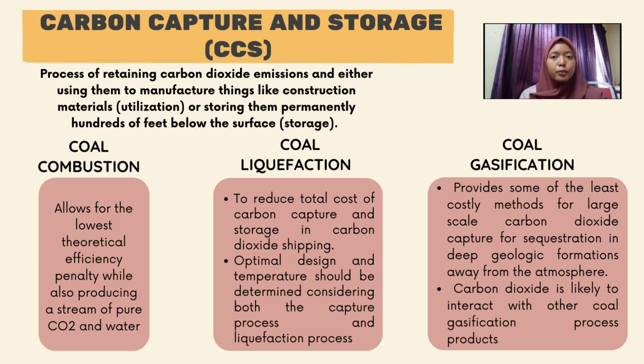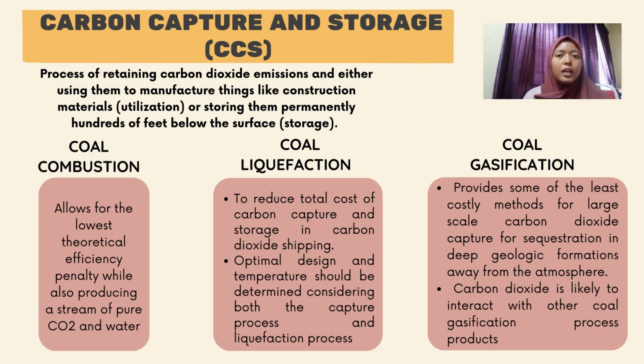Optimal design and temperature should be determined considering both the capture process and liquefaction process, because gaseous carbon dioxide should be liquefied to be carried by ship and it needs more power consumption at lower temperature. Coal gasification provides some of the least costly methods for large-scale carbon dioxide capture for sequestration in deep geologic formations away from the atmosphere. However, the carbon dioxide is likely to interact with other products, hence complicating potential environmental impacts.